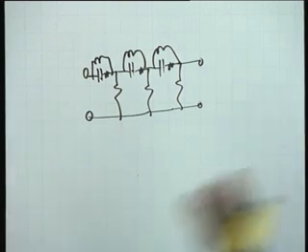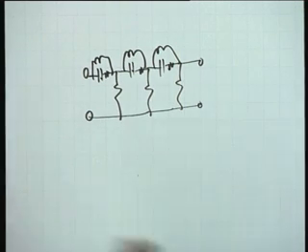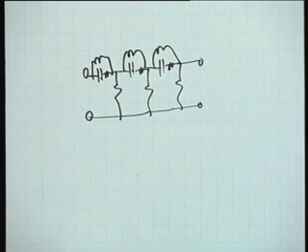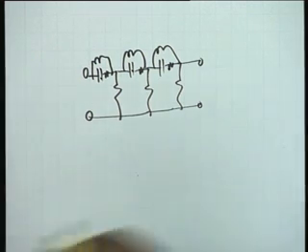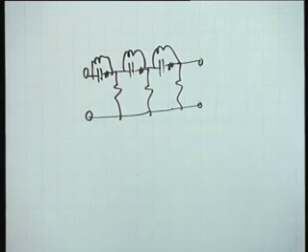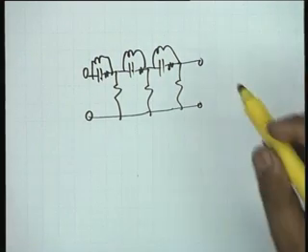No, not anywhere in the S plane. In the left half plane. In the closed left half plane. Okay. Can it have multiple poles? Transfer function. Can it have multiple poles? Not on the j omega axis. It may have elsewhere. On the j omega axis, no. No transfer function can have multiple poles on the j omega axis. Okay. We'll start from here tomorrow.